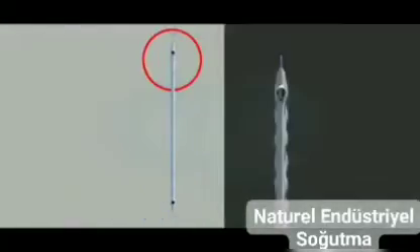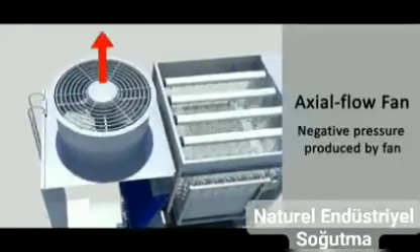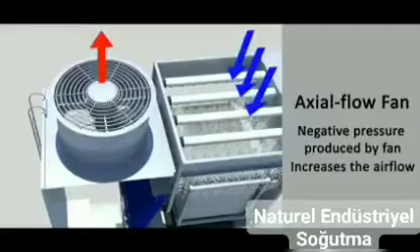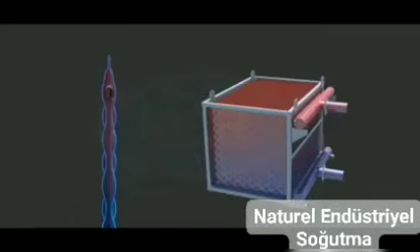Cooling water is uniformly sprayed over each plate cassette via the spraying distribution system, which results in a uniform thin film along the entire height. Hot refrigerant gas inside the cassette transfers heat to the water film. Heat transfer is enhanced in the presence of fan-induced airflow in the direction of the falling water film and partial evaporation of water.